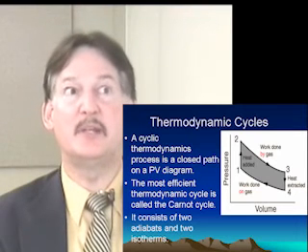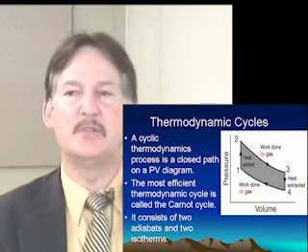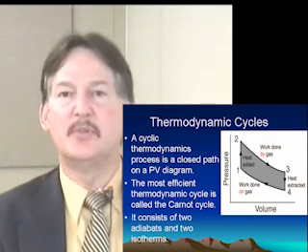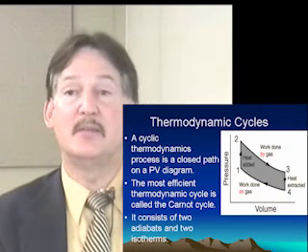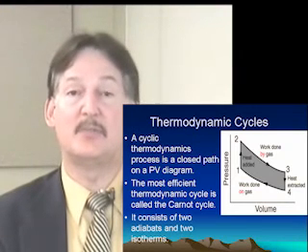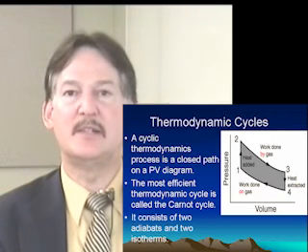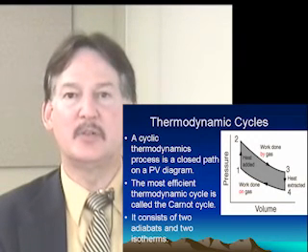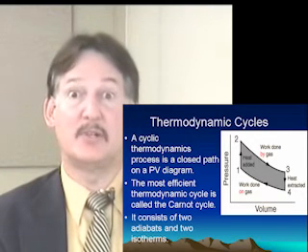We're throwing it away from 3 to 4. So the difference between those two terms, heat in minus heat out, is going to represent the amount of work that we extract from this heat engine. Of course, our goal would be to build heat engines that have the highest amount of work per heat put in that we can attain. That is, of course, a measure of efficiency.